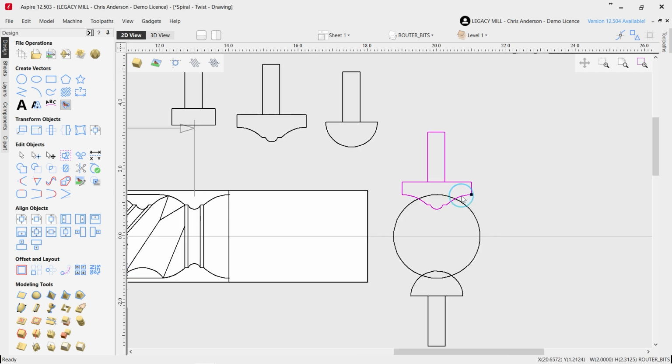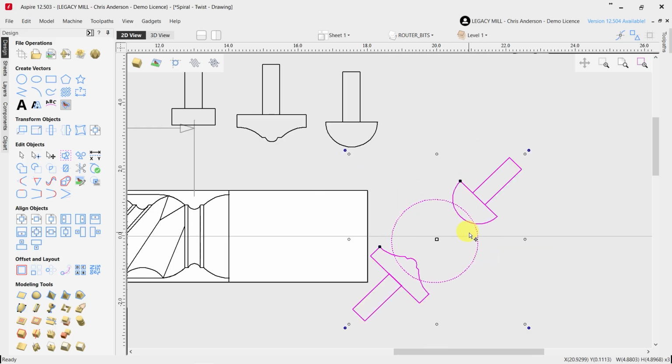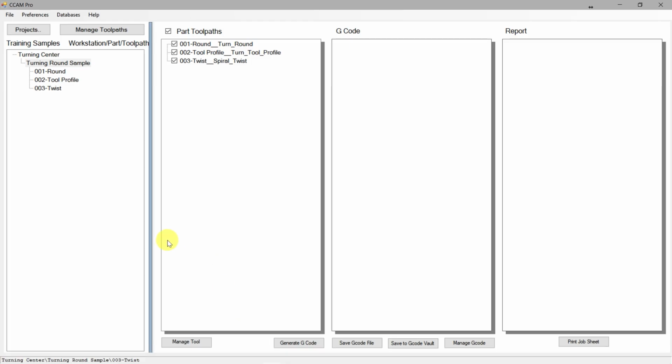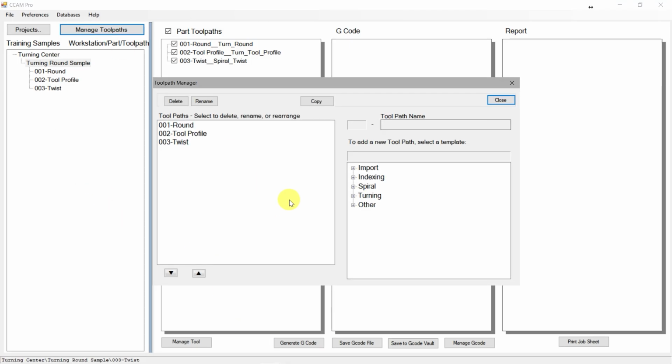Because we just barely finished programming the classic spiral, now we need to rotate this entire thing. The entire blank needs to rotate 180 degrees so that it's in position for the core box cutter to take place. So if we go over here to Secant Pro and manage my toolpaths, this is one toolpath that hasn't been covered yet, but this is really easy to apply. It's under the other category, and we are simply going to set and rotate the A-axis at whatever amount we wish. So we're going to insert that, okay?